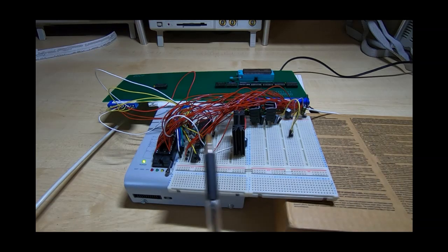The reason I did that is so that effectively I'm taking 4 readings per memory address, and with the original card that flagged up some errors where all 4 readings for each memory location weren't always the same, and that was indicating that the ROMs had not only failed but also certain other ROMs were very slow to respond.